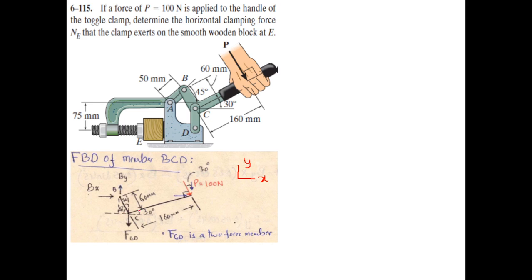Okay. So this edge is actually making an angle of 30 degrees with the horizontal. Since BC and CP are at 90 degrees to each other, this member BC is also making an angle of 30 degrees with the vertical. So it is simply that you have tilted this horizontal axis by an amount X dash, and with an equal amount this Y dash is displaced, right? So this theta and this theta are always the same. That is why this theta is 30 degrees, and this theta is also 30 degrees, right?